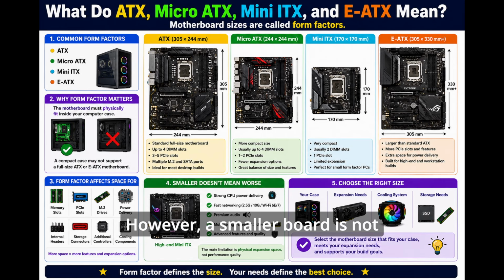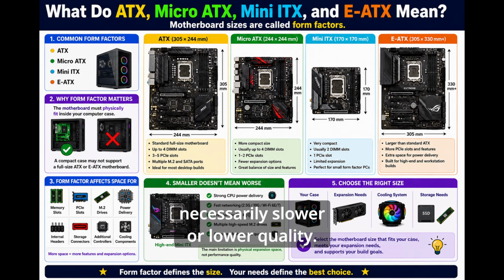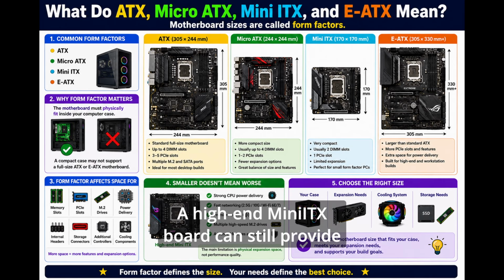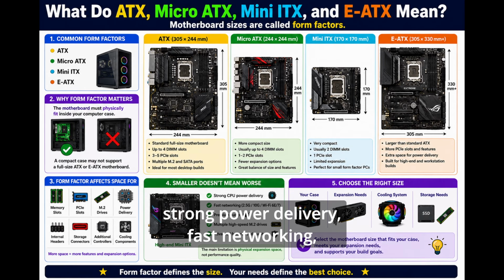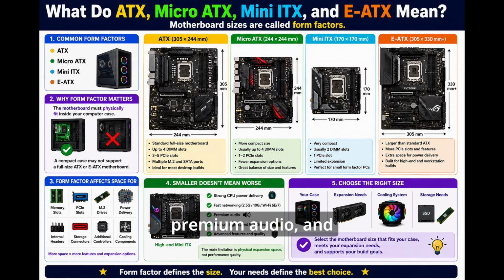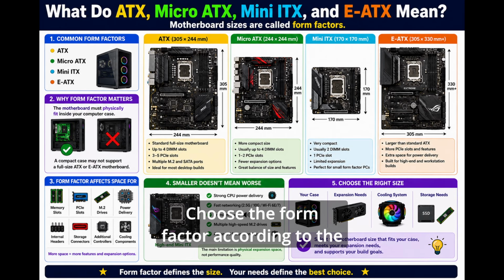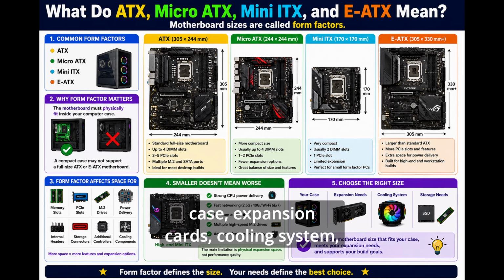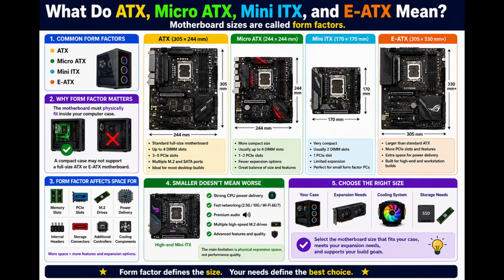However, a smaller board is not necessarily slower or lower quality. A high-end mini ITX board can still provide strong power delivery, fast networking, premium audio, and high-speed storage. Its main limitation is physical expansion space. Choose the form factor according to the case, expansion cards, cooling system, and storage requirements.